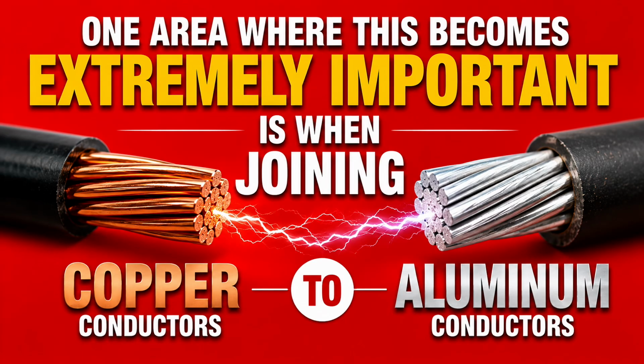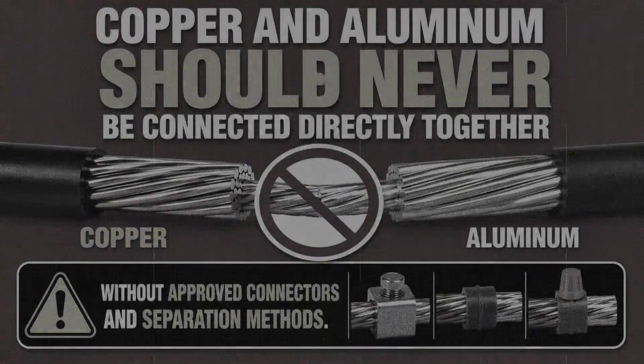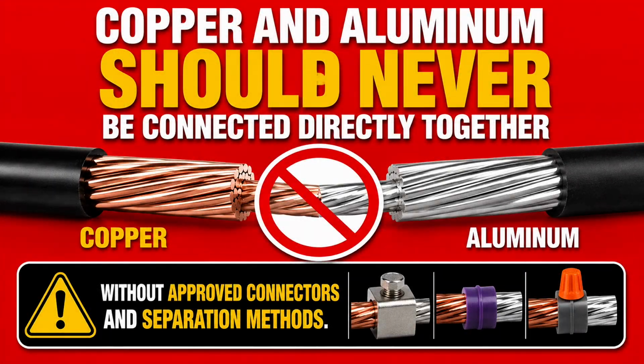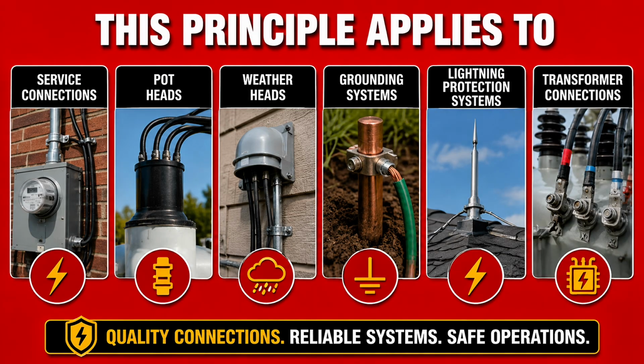One area where this becomes extremely important is when joining copper conductors to aluminum conductors. Copper and aluminum should never be connected directly together without approved connectors and separation methods. Improper connections can lead to galvanic corrosion, causing oxidation, overheating, and eventual joint failure. This principle applies to service connections, potheads, weatherheads, grounding systems, lightning protection systems, and transformer connections.